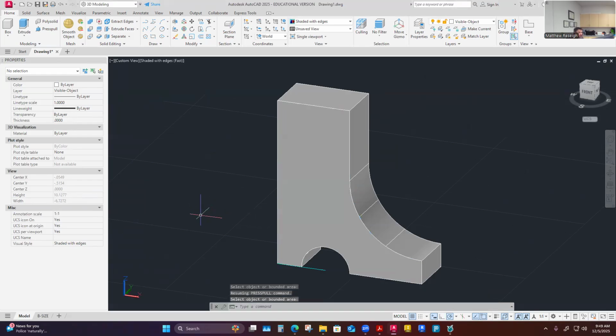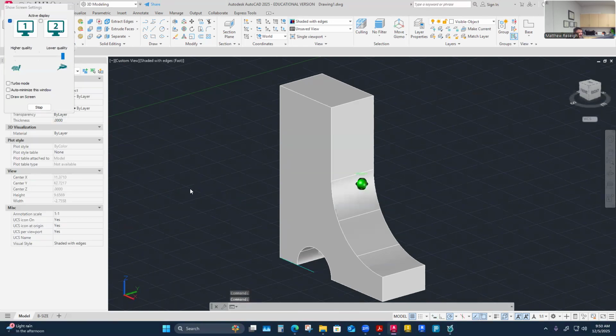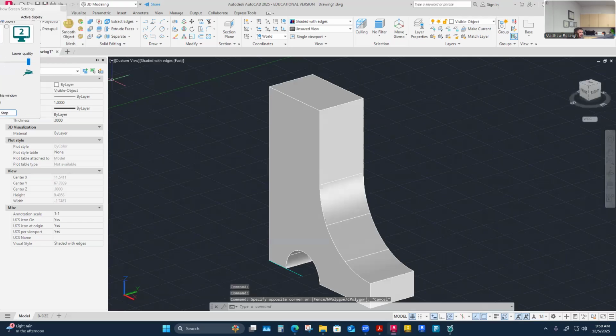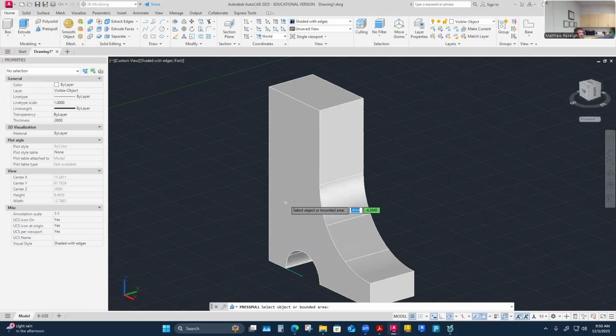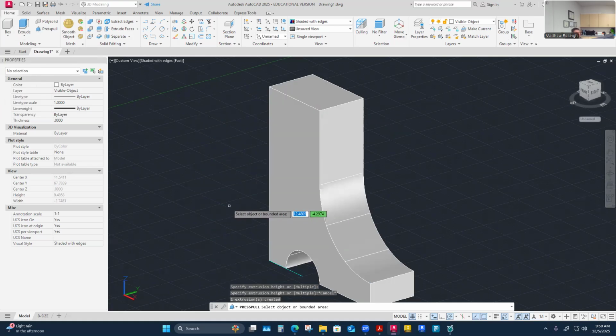So that is how press pull works though. I could, let me see this. Well, you're back in. Okay, cool. It doesn't even really need a sketch to press pull. It'll recognize boundaries of shapes, right? So I think this would work if I grabbed the press pull command and went over here to this surface. I could press pull this thing longer this way. So it's just a really quick way to do what I just did there. It'll identify these surface boundaries without even a sketch. And so anyway, that can be pretty handy.